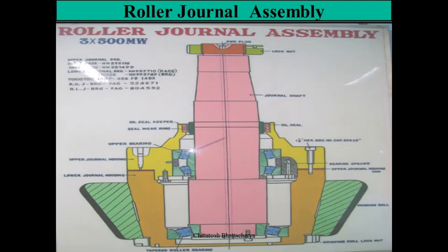There are vane wheels placed across the mill body surrounding the bowl, through which hot primary air is coming, and it is carrying the coal to the top of the mill body. This coal, along with primary air, is going to the classifier.